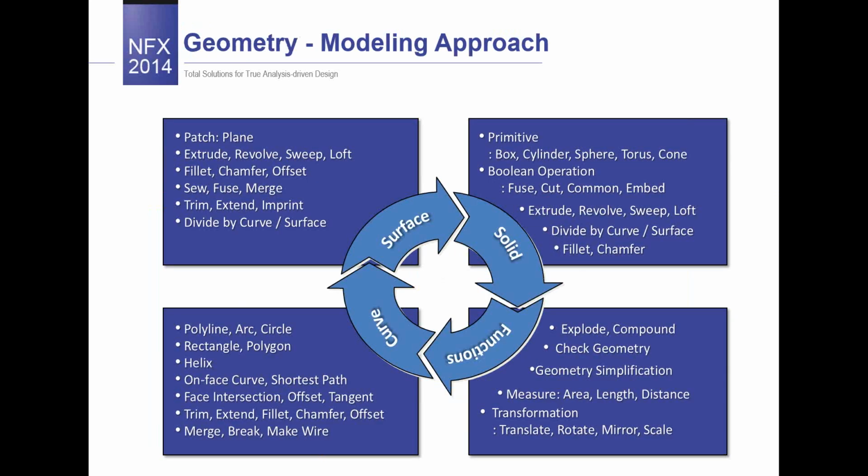Okay, so in the analyst mode, we have access to many geometry tools. Basically, we can create all types of geometry, starting from the point and ending with the solid. I will show you some practical examples during the tutorial session. To create the geometry, we can use, for example, polylines, arcs, and curves. After that, we can transform these entities to 2D and 3D objects. Another step is extrusion, revolving, sweeping, or perhaps lofting the geometry.